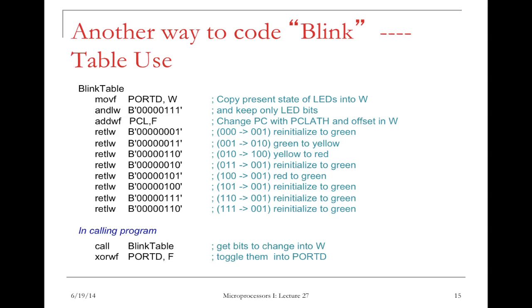When the microcontroller is executing this instruction, this ADDWF, the value in PC is pointing to this location. Okay? The address, the value of the PC is the address of this instruction. This is an addition operation. It's going to add W onto this PCL. Right? ADDWF is add two numbers. One is W, the other one is this PCL. Comma F, that is to say, the result goes into that register. So that's PCL. So what do we add to PCL?